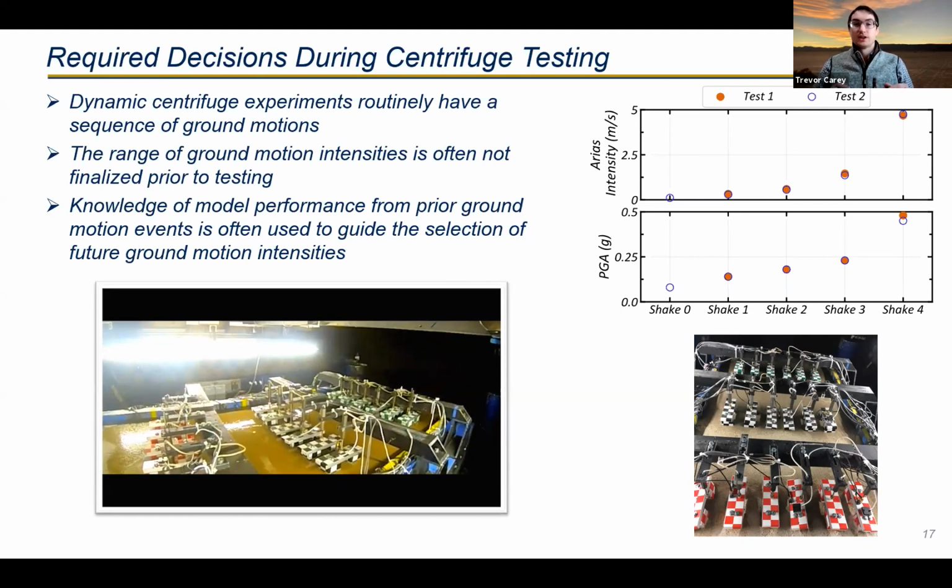So you can imagine if we didn't have the correct shaking or the correct intensity of shaking, we might have immediately buried those structures and made them settle early on in the process. So having a good ability to recognize that, yes, we don't want to have this happen immediately, but how do we get to a staged approach and cause these to settle over time among different phases.